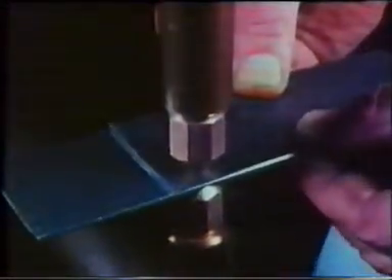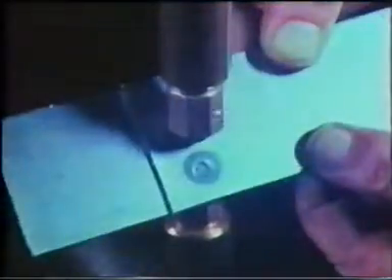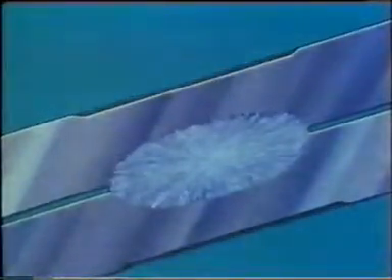Correct pressure or electrode force is essential. Too little allows the molten metal to escape, causing surface burning and other defects. When the weld is opened up, the splash of exuded metal is clearly seen. Too much lowers resistance and heat at the junction. This causes deep surface indentation, compressing the metal walls surrounding the weld nugget and weakening the joint. Indentation should not exceed 10% of the sheet thickness.